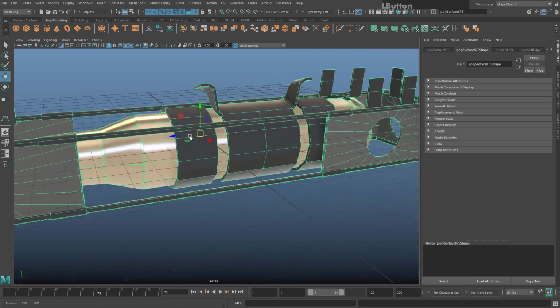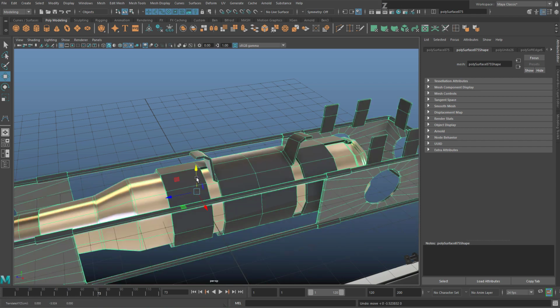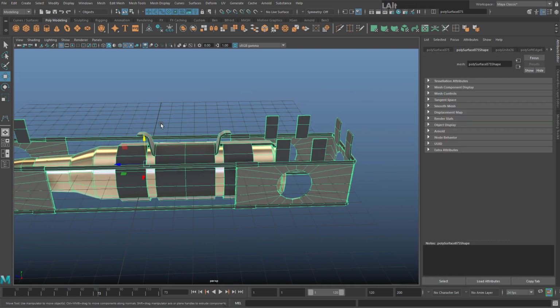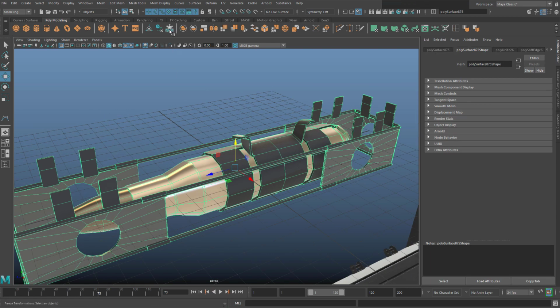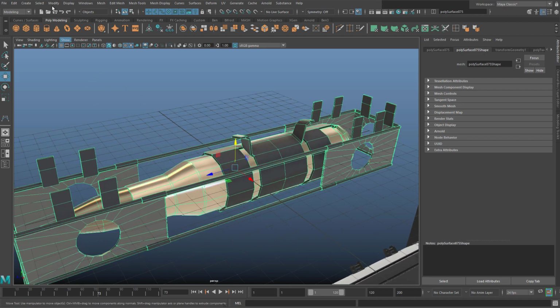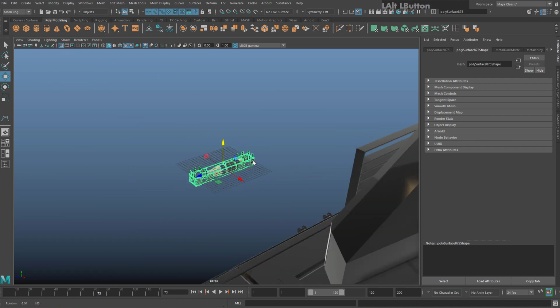So this bullet is now exactly in the middle of my scene. If I move it this way, you can see it is exactly there in the middle. So that was holding X to snap to grid. That's exactly in the middle. That's great. Once it's there, you're going to need to do Freeze Transformations while it's in the middle of your scene, and then Delete History and Freeze Transformations once in the middle of your scene. And finally, go to Modify, Bake Pivot, so the pivot stays in the middle for the next step.